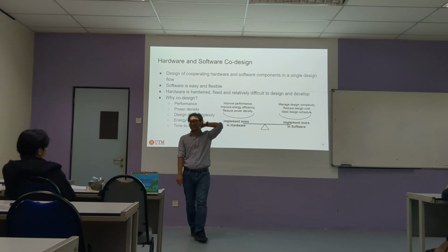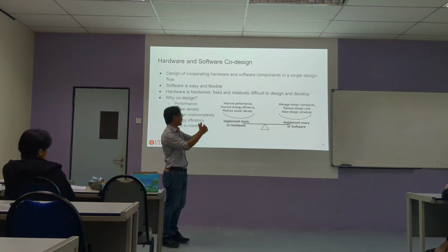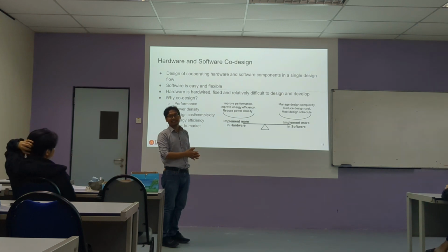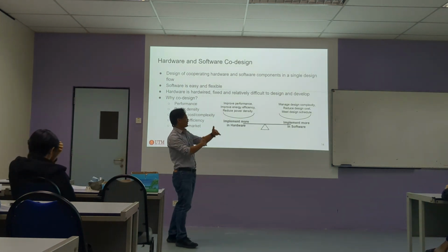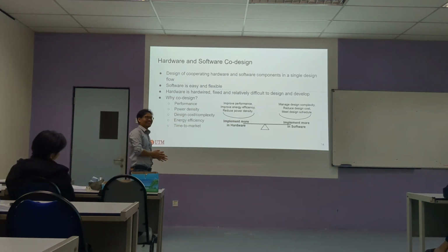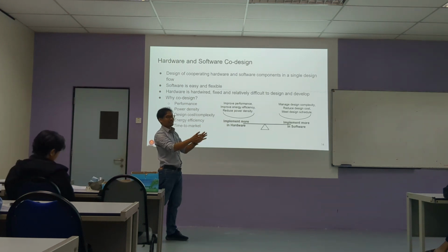The solution, they say, is to use the high-level synthesis methodology. That's one solution. You can design your sorting algorithm in C and then use the tool to automatically get your RTL, so no need to write manual RTL. For the sorting algorithm, I think it takes like 10 seconds to get your RTL. But is it efficient or not? That's another question, right? Is it more efficient to write your RTL manually, or to generate your RTL from C using these tools? Which one is more efficient?